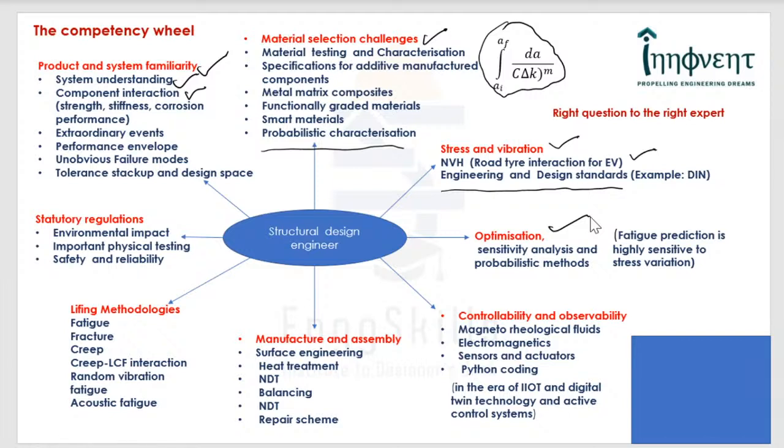To impress upon you the need for sensitivity analysis, a very simple example is, let's say you're trying to estimate the life of a component, and assuming that it is stress based, if you are making an error of 5 to 10% in the stress computation, then the predicted fatigue life can vary by 30 to 40%, and that is what we call sensitivity. That is, any structural response may be influenced by several parameters, and the parameter that influences the structural response the maximum is the parameter of interest.